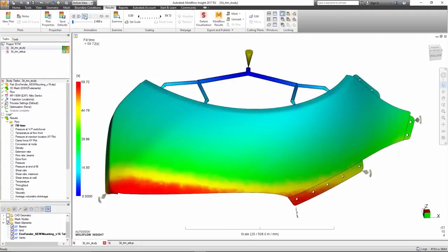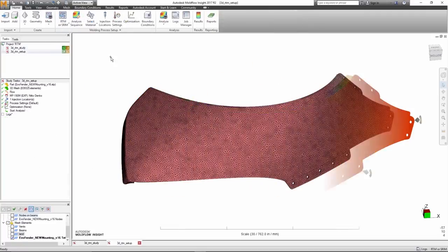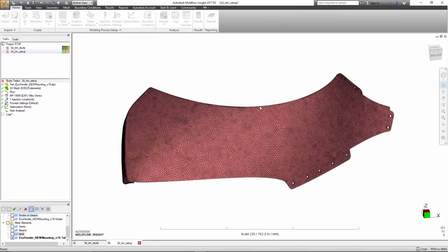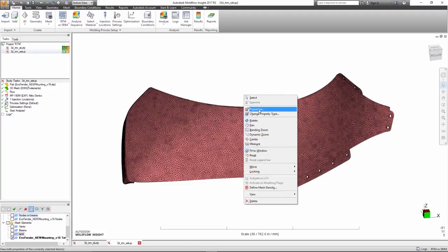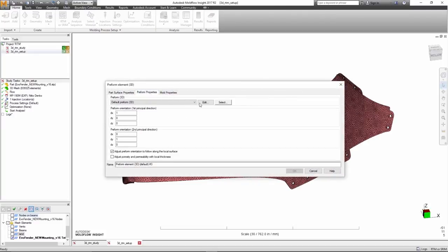The strength is provided by the carbon or glass fibers, while the resin, often an epoxy, forms the glue that keeps the structure together. The lightweight but extremely strong properties make this a very appealing process for automotive and aerospace applications, where these properties are highly desirable. In the last few years, material suppliers have developed fast curing grades, especially for automotive applications.